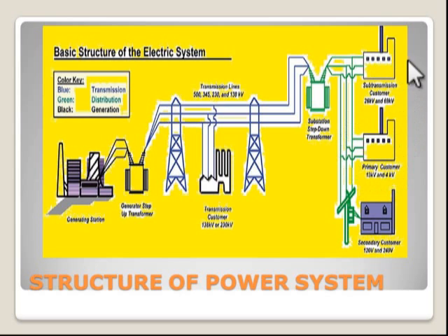So sub transmission customer, here it is 26 kV and here it is 69 kV. These are all the high level load customers, and here we have primary customers. Primary is 13 kV and 4 kV, and secondary is our residential loads. It may be 3-phase loads or single phase loads. Here we have to utilize our loads. So this is the basic structure of our electric power system.